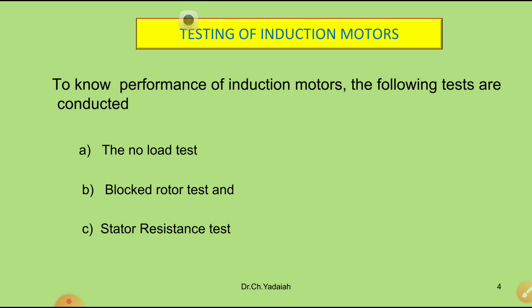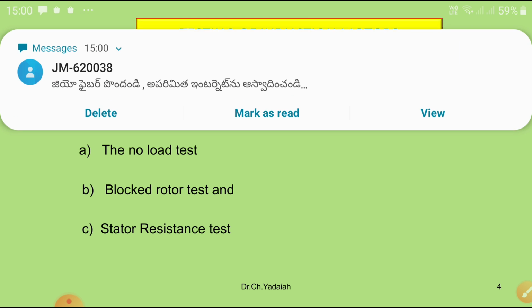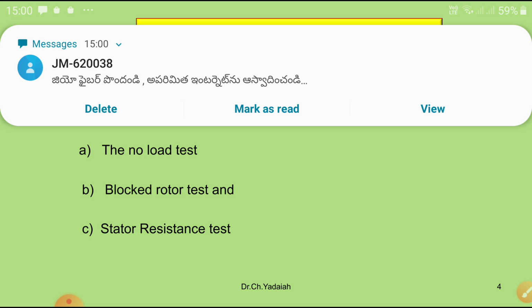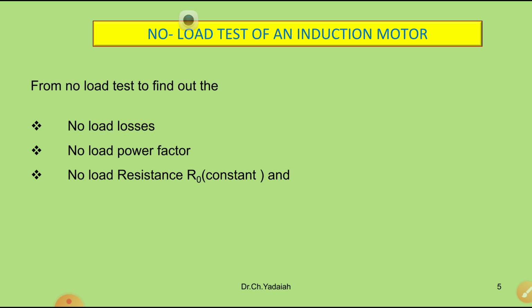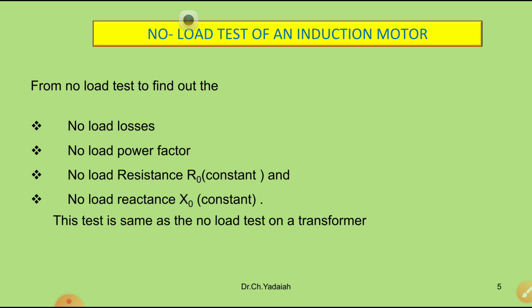Similarly, here we are going to conduct the same test on a three-phase induction motor. Let us see what values are required. From the no load test, we find the no load losses, no load power factor, no load resistance R0, which is a constant, and no load reactance X0, which is constant. This test is the same as the no load test on a single phase transformer.